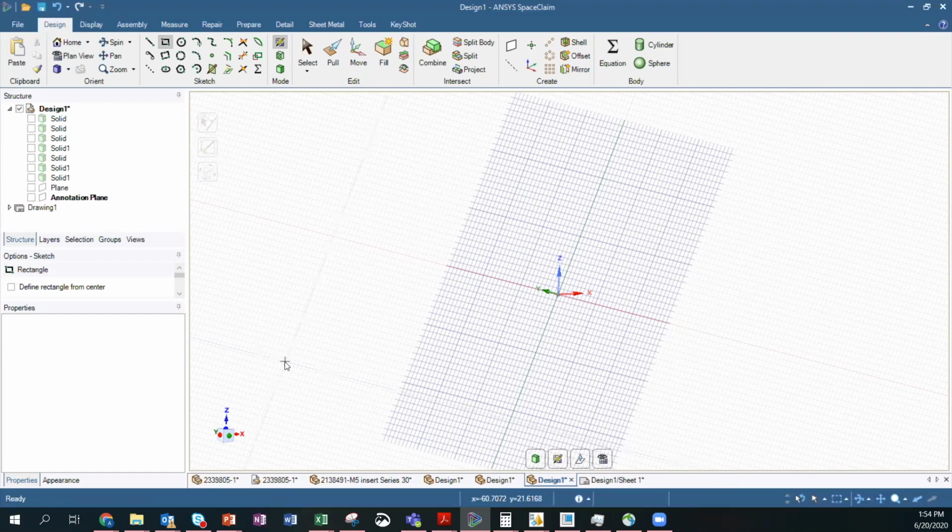But how do you choose the material? You look at how it can be manufactured, and the cost. There are many factors: cost, manufacturability, and the environment in which it's going to function, the functionality. So for example, in your case it's just going to be a camera sitting inside your home. It's an ambient condition, so you don't need an extreme material. You want something much cheaper, not very expensive. So you go with a plastic that's manufacturable and also cheap.